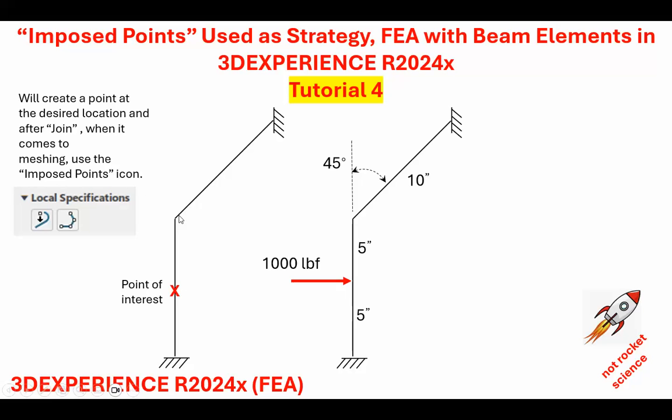If this is not joined, you have to join these lines separately when you mesh this thing, unless you ask for the nodes which are close to each other to within some tolerance to be captured, there may be duplicate nodes here. So that's what I'm going to do. I'm going to make sure that this is joined.